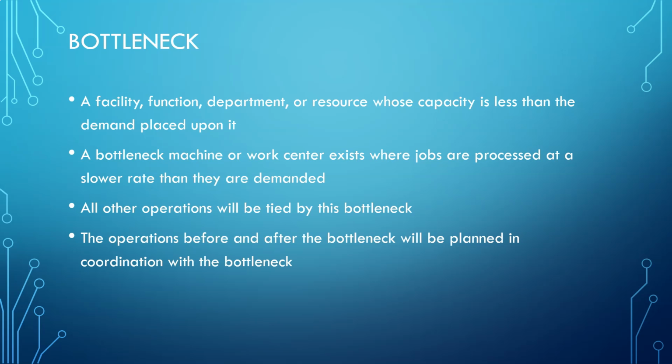The capacity of one workstation can affect the capacity of the whole system. To determine the throughput capacity of workstations, we can conduct capacity analysis. The workstation that has the most limiting factor or constraint is called the bottleneck. We can identify the time to process an item through each station. The total time to produce one unit is called process time.